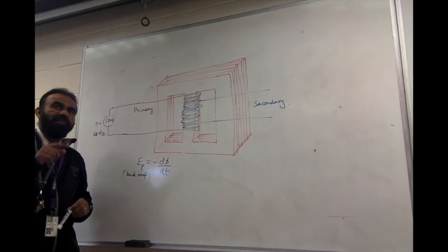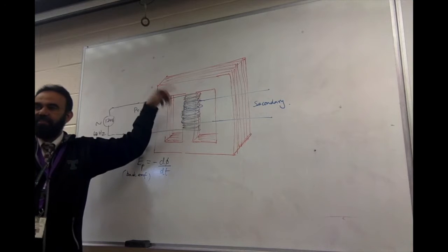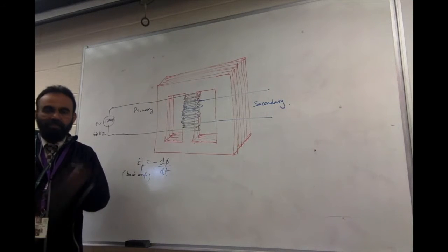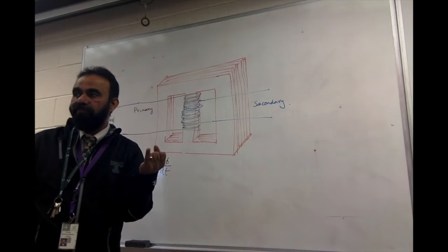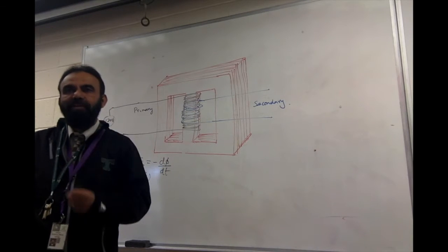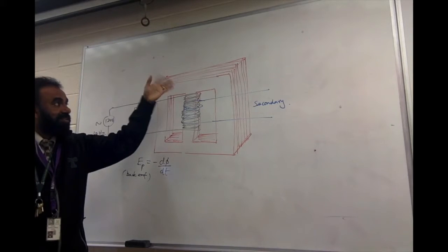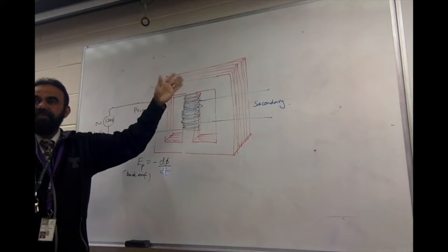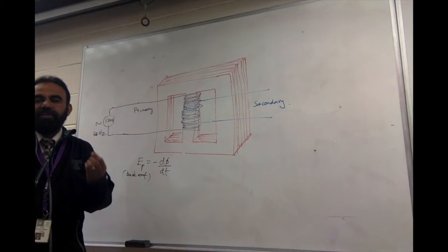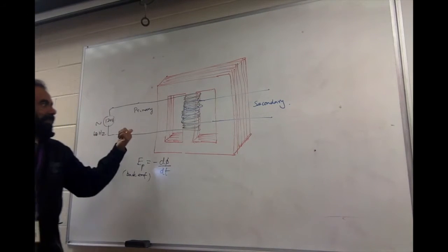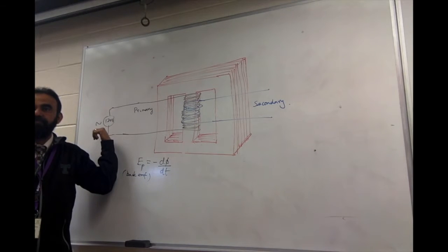Now why 119.999? Because there is some loss here still. It could be eddy current loss, or heating loss in the wires, magnetic losses, although we have tried to prevent it, but still some magnetic leakages can still be there. So you won't get 100% return, but you will get very, very close to what you supply.